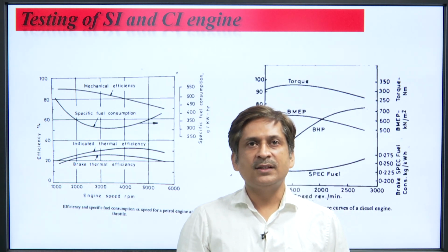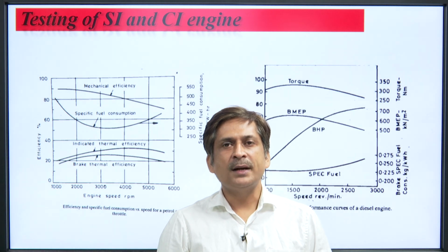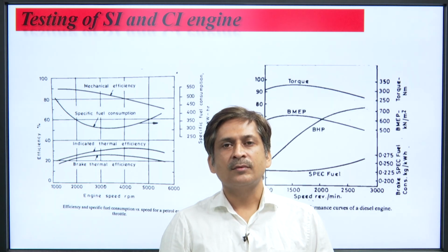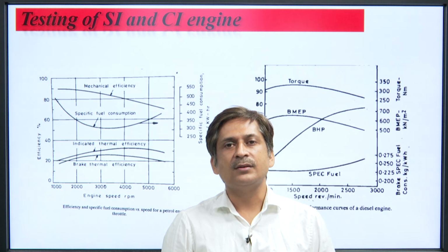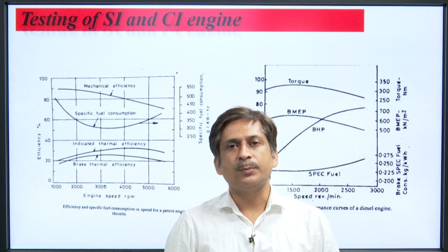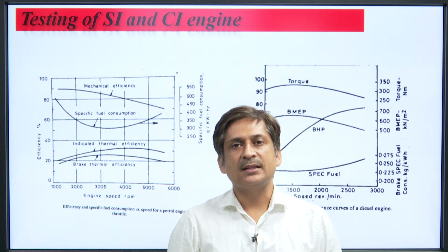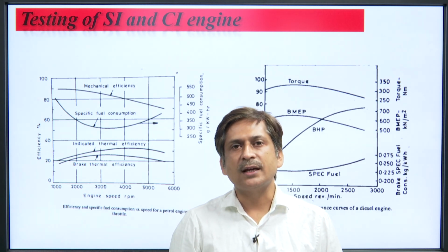Now, come to the testing of SI and CI engine. What do you mean by testing? Testing means if a manufacturer is predicting that this engine is of 5 HP, that is 5 horsepower or 5 kilowatt power, we have to check that engine, whether it will give you 5 kilowatt power at full load or not. That is called testing of SI or testing of CI engine.